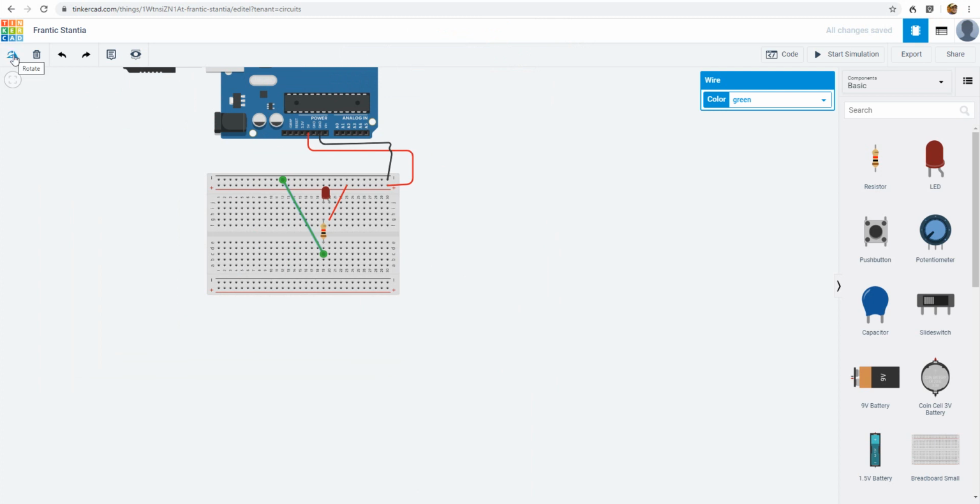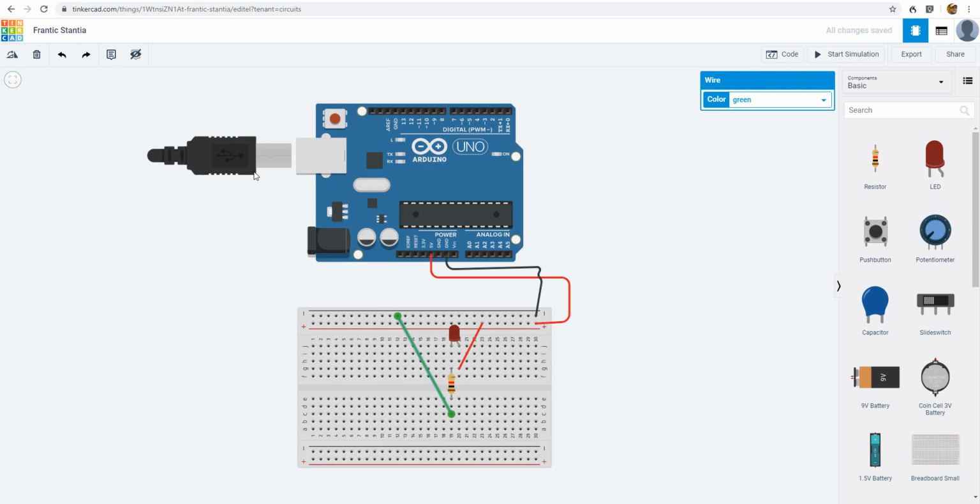There's this option that actually brings the whole picture inside. Then you can actually visibly see your animation. Sorry, this one. Now, in order to see if your circuit works or not, click on Start Simulation. And it did work. You saw that the LED light came on. If I stop the simulation, it changed color.